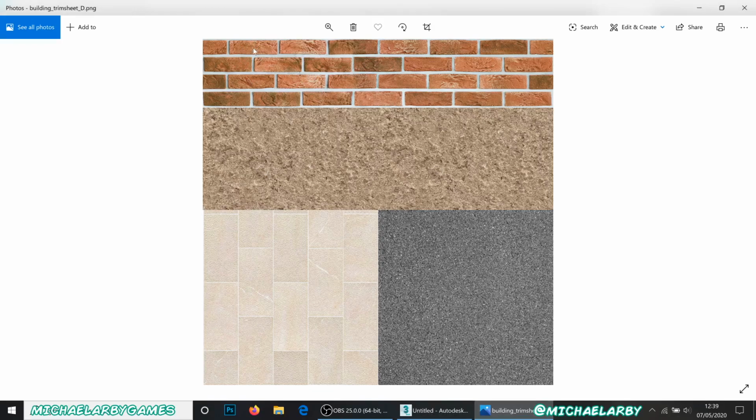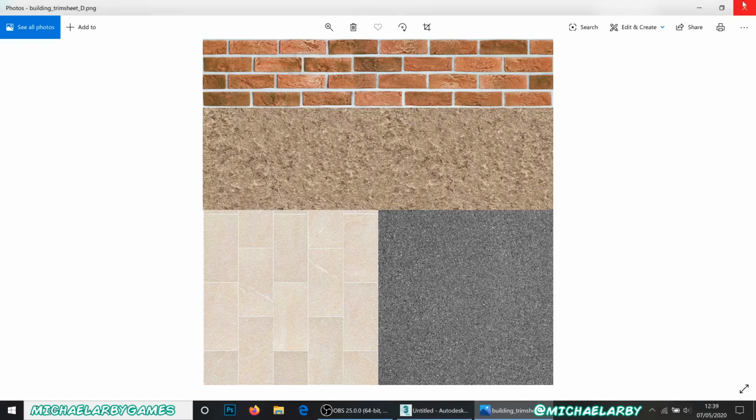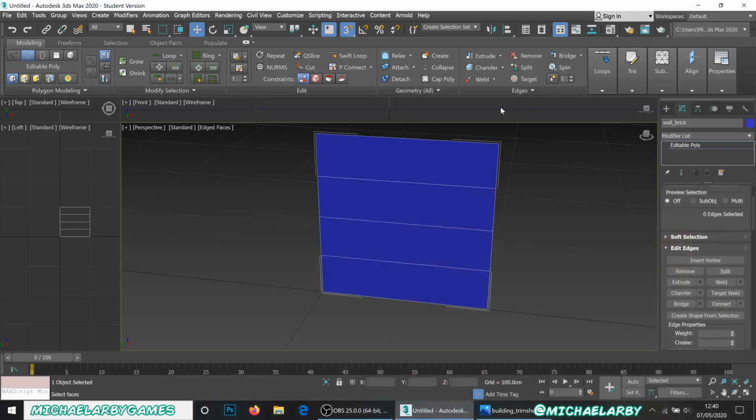I know just from experience and doing the research that a brick is about 75 millimeters tall, which means that 2 bricks is about 15 centimeters, 4 bricks is about 30 centimeters. So if I squeeze those bricks along here, it's going to be just not quite right, 25 centimeters to 30 centimeters. We're squishing it in a wee bit, but it'll be close enough that it looks okay. So what this effectively means is that each one of these strips is going to have 4 bricks in it. So why don't we actually just apply those bricks now?